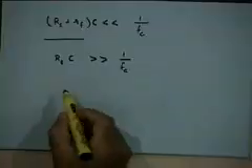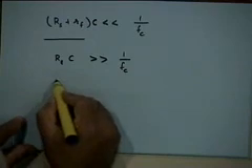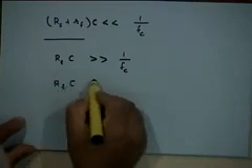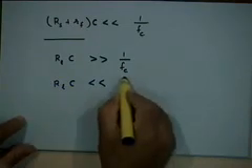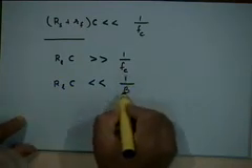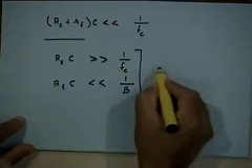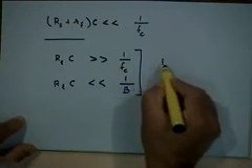So let us say the bandwidth of the message signal is B, therefore the highest frequency present in it is B, and therefore the time interval of interest is 1 by B, right? So what we would like to have in addition is that R_L C should be much less than, complete the sentence, 1 by B. These two conditions we can put together to say that